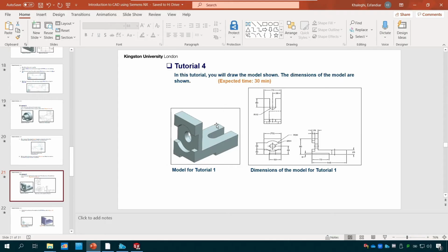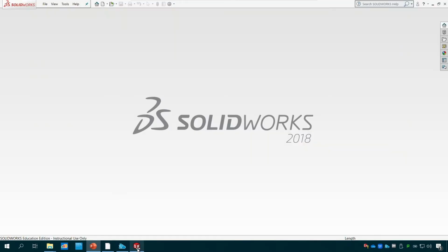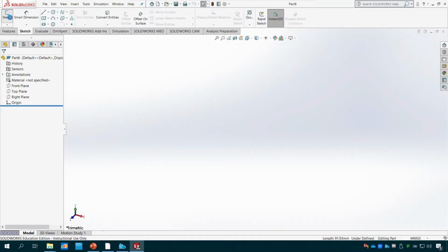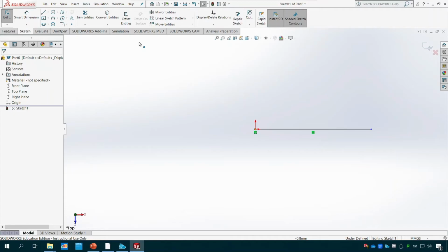So what I'm gonna do, I'm gonna go here, make a new file. Again, make sure it's a model, it's a part. Click on OK. And from the feature, I go to the sketch, click on a sketch. Let's say I'm gonna pick up that plane again and make the line like that. That goes straight. And I'm gonna make one more line in here as well.